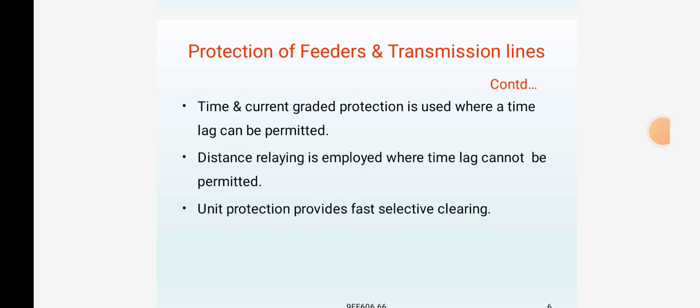In single bus bar, the layout is meant only for small stations. In the basic scheme, the generator, circuit breakers and switches, meaning isolators, are provided respectively, while for the step up transformer, present day practice does not favor such a large number of circuit breakers.